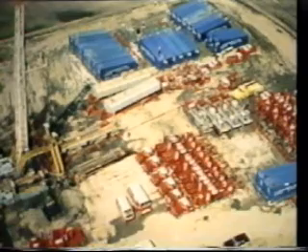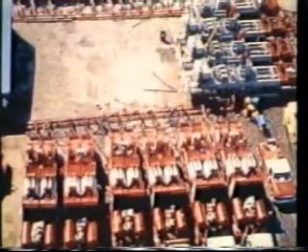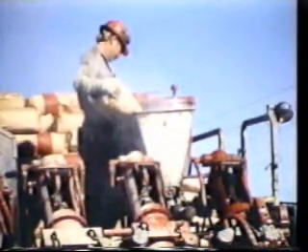Typically, a large amount of specialized equipment is required for a fracture treatment, particularly a massive one. The fluid and proppant must be steadily blended and sent to the rows of pump trucks which work together to pump the mixture into the well at a steady high rate and pressure.